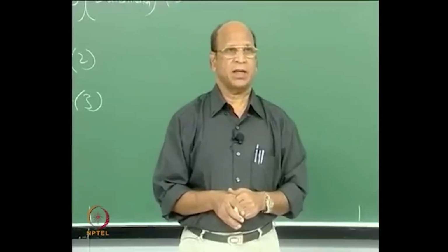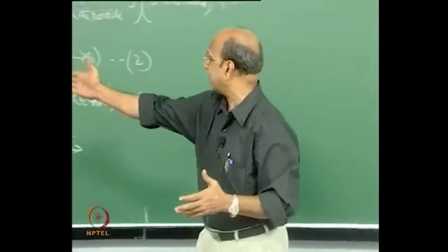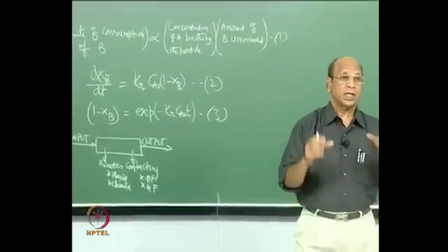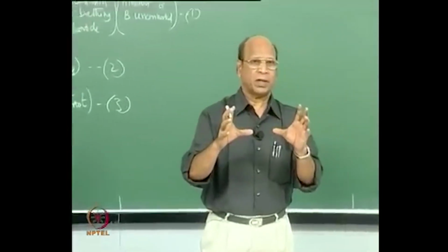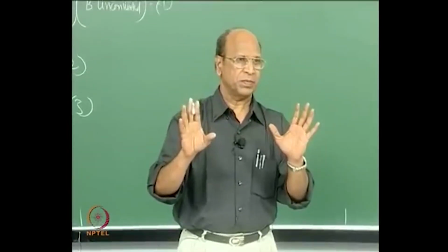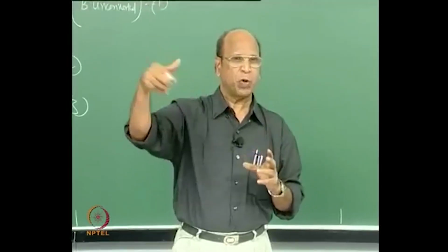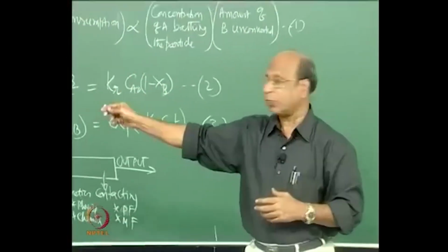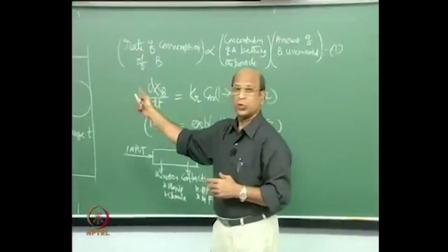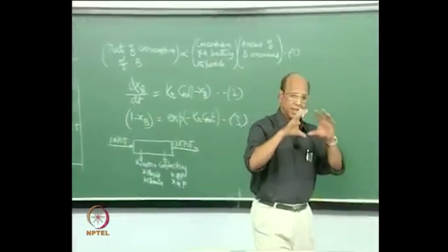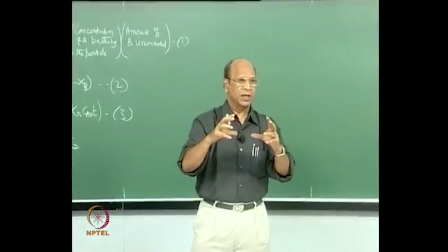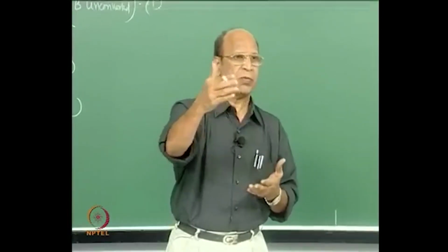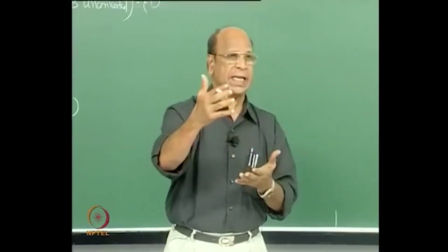Deactivated catalyst, where the deactivated catalyst is almost the same. In fact, a similar model is used for deactivation, because all our catalyst particles are porous particles. So that must be homogeneous. The deactivation goes here in the reverse way. Here we are converting the reactant into product, but there the entire particle is very active in the beginning, and during the reaction there is a reason for it getting deactivated.